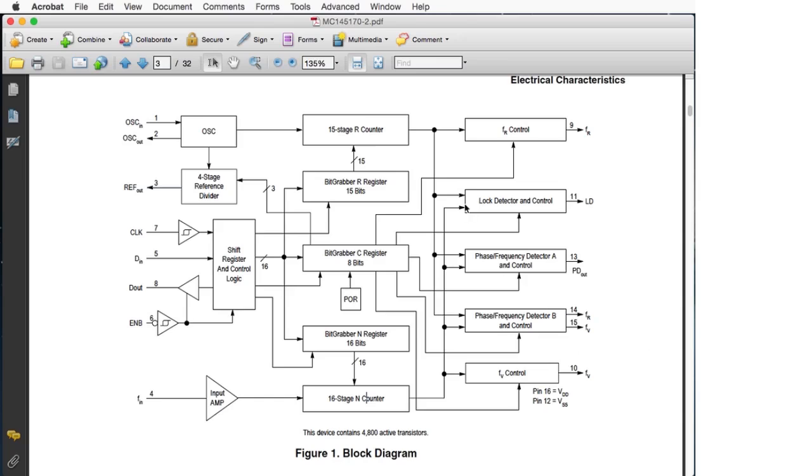And then you've got a lock detector as well. Both of these are applicable to all PLLs. Basically, it compares the reference frequency, which should be 5 kHz or 10 kHz, against the frequency coming in from here. Like I said, this is not necessarily exactly 5 kHz or exactly 10 kHz. It could be out a bit. When it's wrong, this phase detector senses that error in frequency, whether it's leading or lagging in pulses, because effectively that's what we're doing.